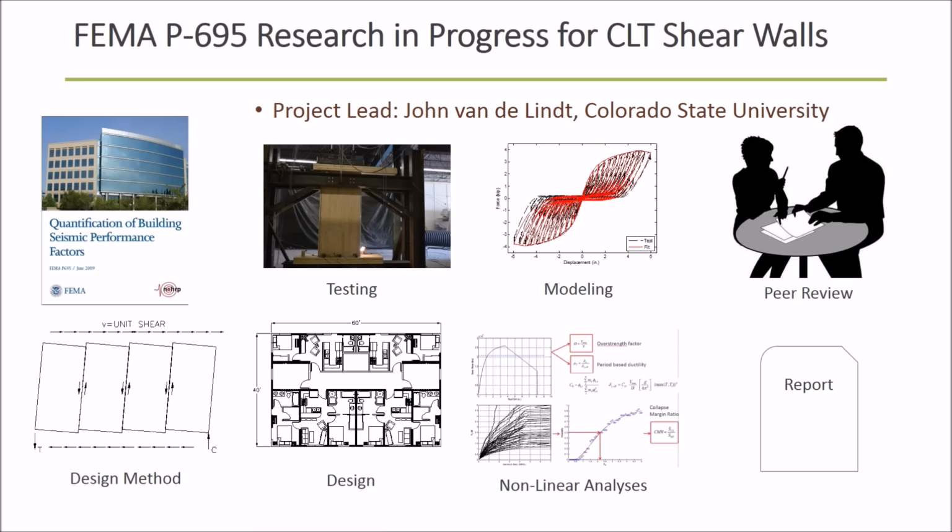Now, when they complete their research within a year, it's not going to be in ASCE 7-10, it's not going to be in ASCE 7-16, which is pretty much already written and not published yet. So we're not going to have that code-adopted seismic shear wall system for a while, but when this research is done, it may be an advantageous route to do an alternate means for a CLT shear wall system.